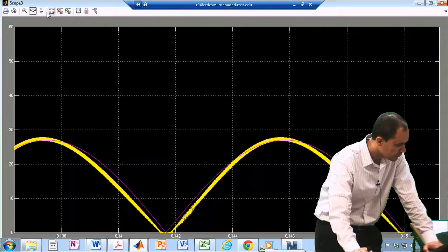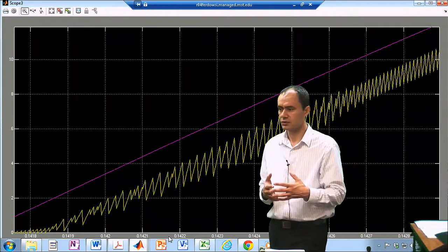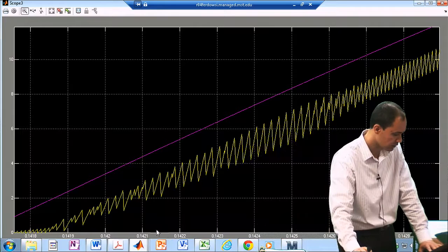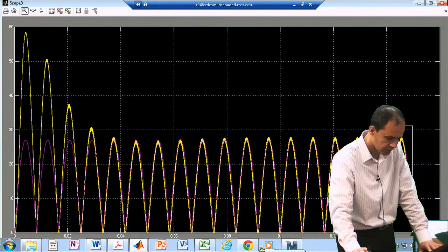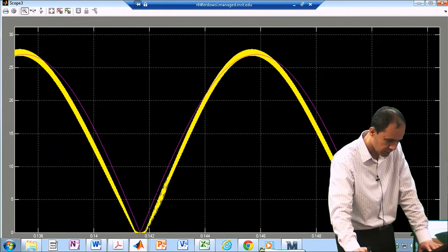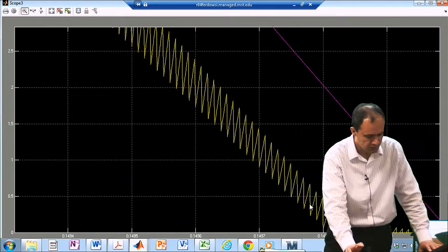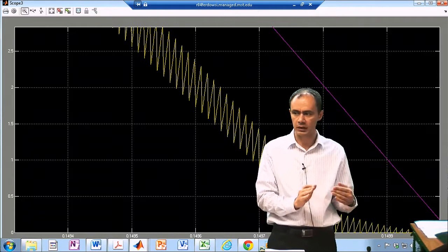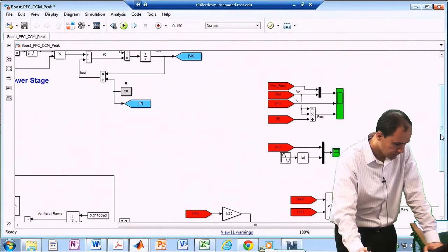And then there is a little bit of a problem. You can visually observe it over here, some subharmonic oscillations in your current signal. And they also appear on the other end of the signal, which is somewhere around here. Actually, this one is doing quite well, but sometimes it happens. The subharmonic oscillation problem occurs when you are getting close to 0, basically. And we are going to talk about why that is.